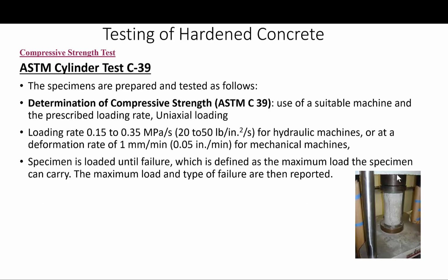So how do we determine the compressive strength? Again, I'm talking about the tests according to ASTM C39. Once the specimens have been capped, they are ready for testing. The tests may be carried out in any suitable testing machine. Basically, the description of the apparatus is that two hardened bearing blocks are used, a solid one that the specimen sits on, and a spherically seated one that will bear on the upper surface.